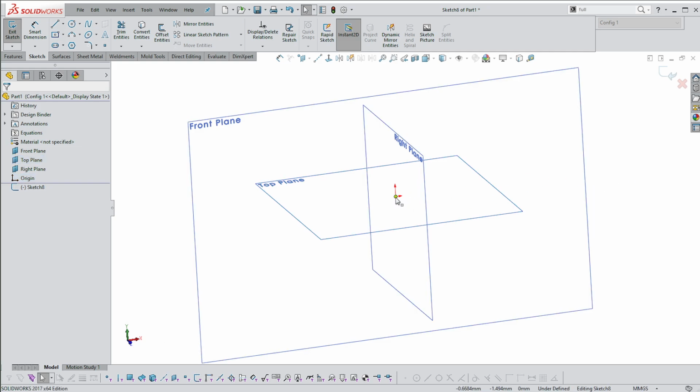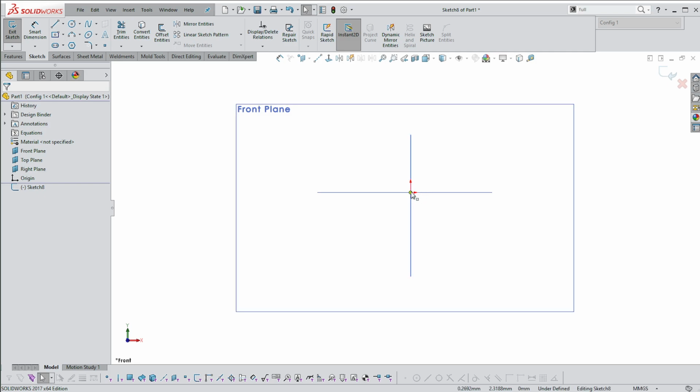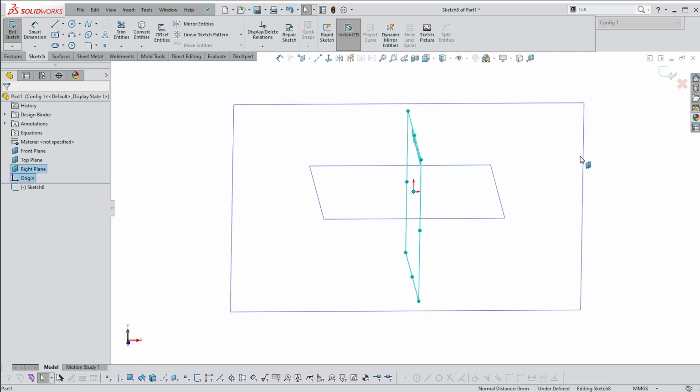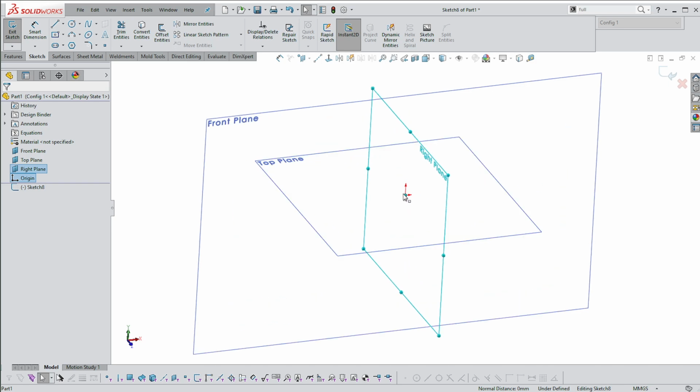If I do the same for the right plane, in fact, let's just go back to our normal two and do that. So that point also coincides with the right plane, and then the red arrow points upwards to coincide with it. So the way to think about datums is that they're actually planes. You will always need two datum planes, even though in normal language you're going to be talking about datum features or datum and the datum point. So the point represents two datum features.